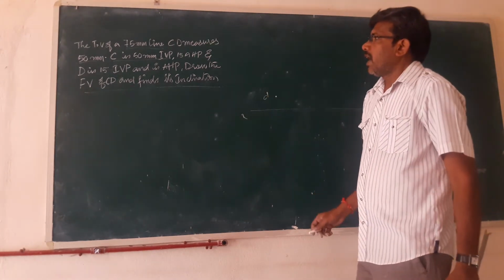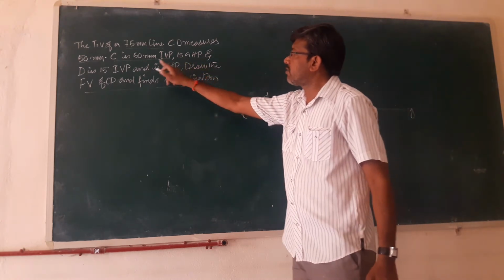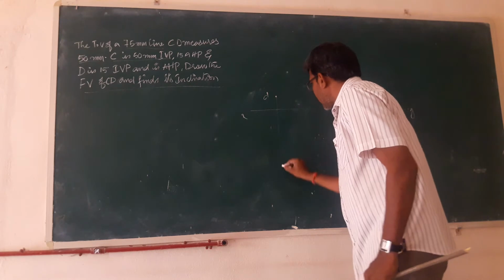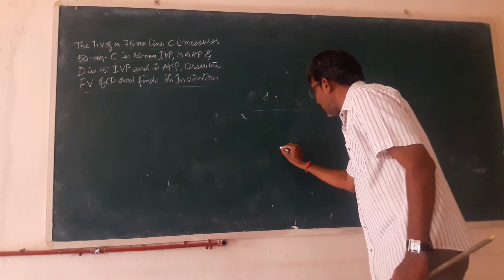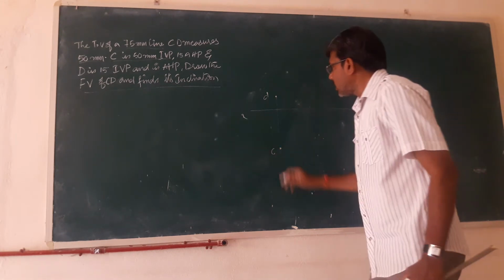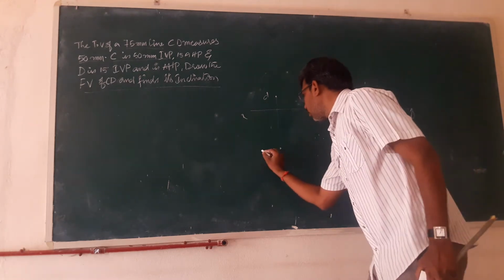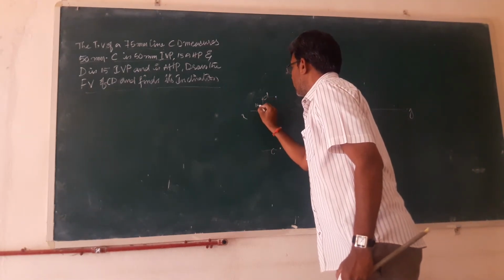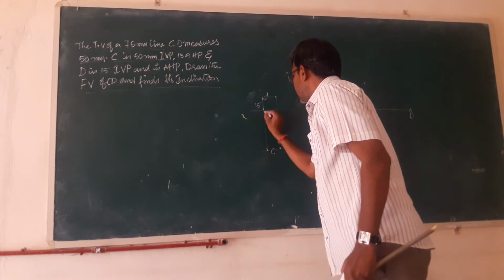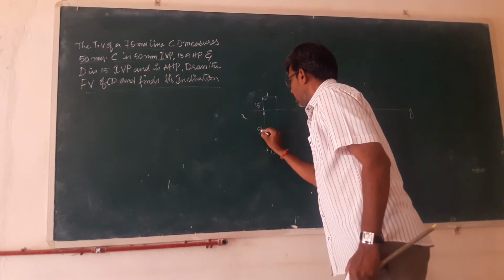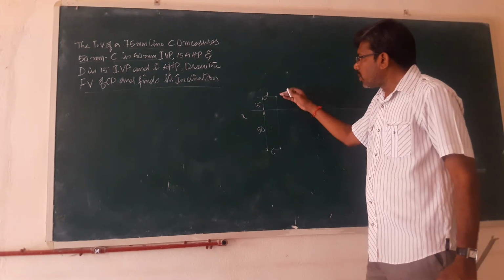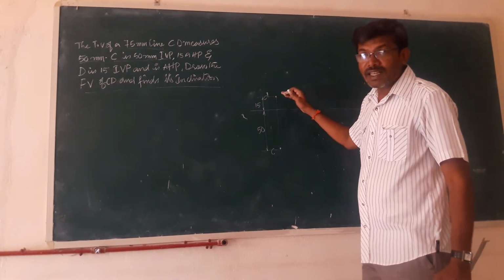And next, this is 50 mm in front of the vertical plane, so I will draw a straight line here and put a point C. So this is C, that is 50 mm. You can write down the dimensions here. So this is 15 and this is 50. Is it clear?